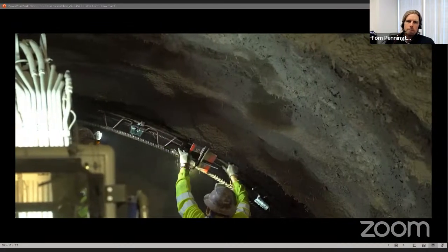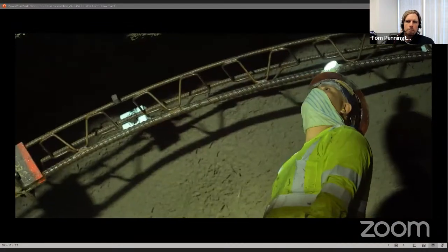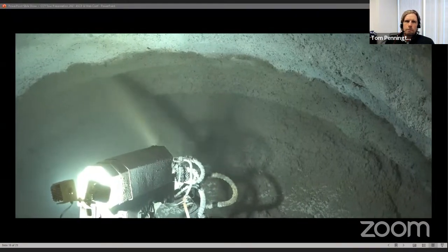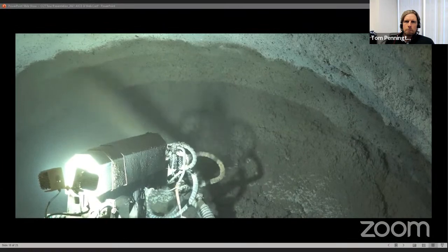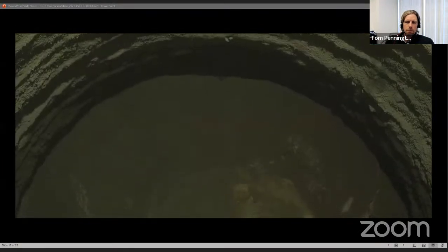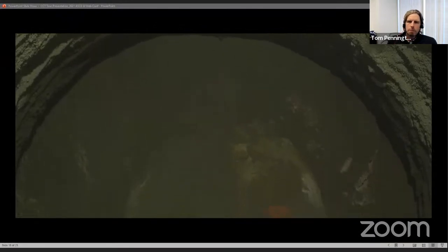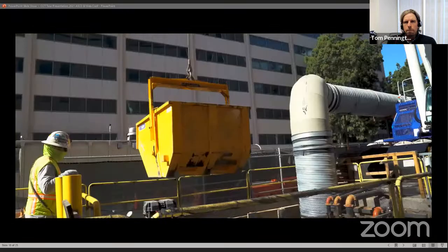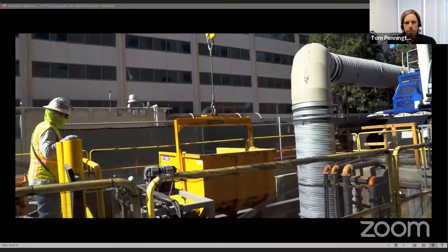The shotcrete initial lining with embedded lattice girder creates a composite cylindrical shell of support to the ground around the excavation. The initial shotcrete lining is cured to an adequate compressive strength of approximately 75 to 100 psi. This usually takes 30 to 45 minutes, after which the crew can begin the next advance of the excavation.